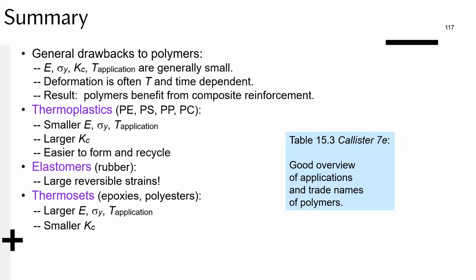And then elastomers are materials with extremely high elongation at break and highly deformable materials that can be thermosets due to the vulcanization. And the good thing about them is that they have a reversible strain. So rather than experiencing necking like plastics do, they extend and can go back to their original length pretty easily.